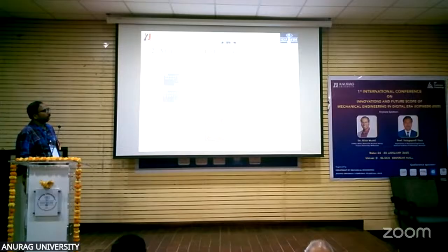During the drilling operation, the thrust force is calculated. After completing the experiment, the delamination factor has been determined. Delamination is the damage occurring around the hole. It is a numerical value determined by Dmax, the maximum diameter, divided by the tool diameter. Here an 8 mm tool diameter of HSS material has been used.